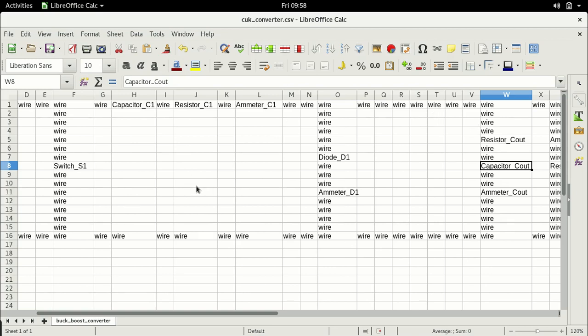This is a closed path, and this closed path has only a negligible resistance. This resistor C1 and this resistor C out are parasitic resistances of the capacitor. They cannot block current, which means we cannot leave this path as it is, because this capacitor and this capacitor have literally very little impedance between them. So it's like connecting two voltage sources in parallel, and these two voltage sources need not be equal. So therefore there must be some kind of a current blocking between them.